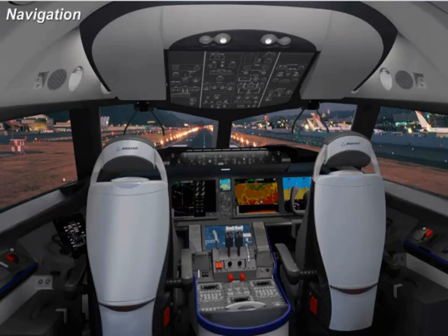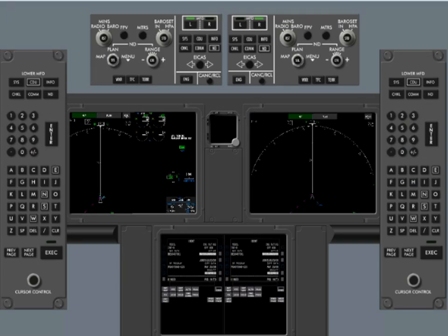In this module, you will learn how to navigate to the electrical system indication and control ESIC display, and learn about the features of each of the display selections. You use ESIC to control or lock out contactors that are not part of CBIC. Use the Captain Inboard MFD to access the ESIC function.